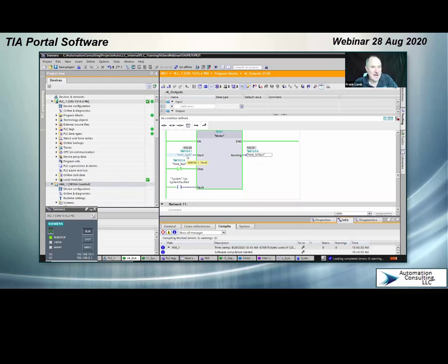I'll show you how the auto sequence works for this. If I'm not in run mode, then it's going to automatically stop this. Inside of this was just a typical hold-in circuit, and the output for that usually would have been a physical output. But again, I don't have a real PLC here, so I just used an HMI indicator.